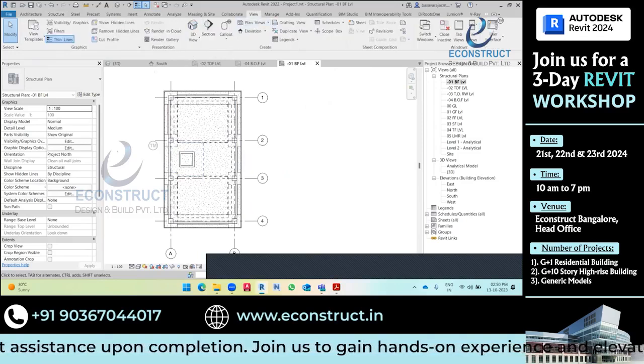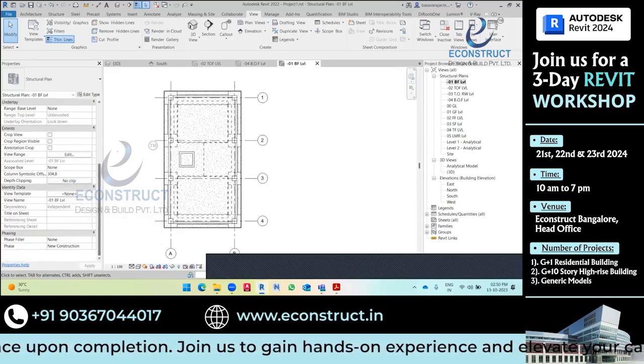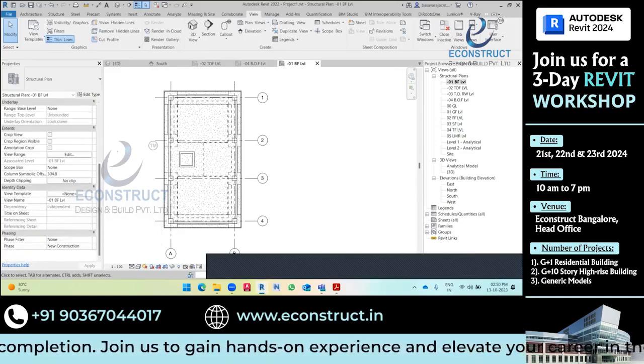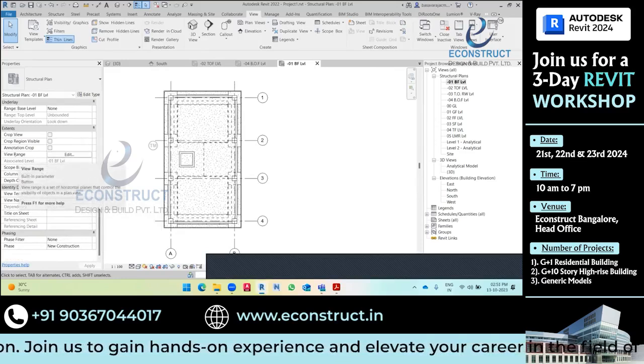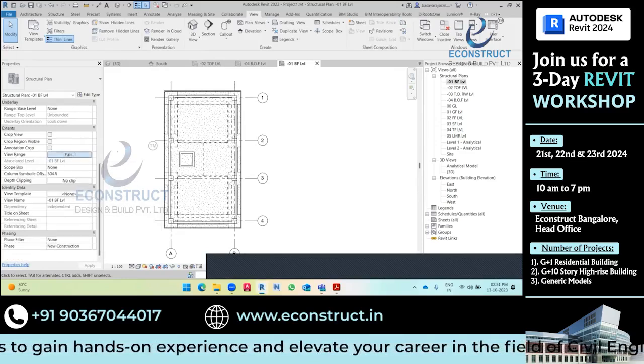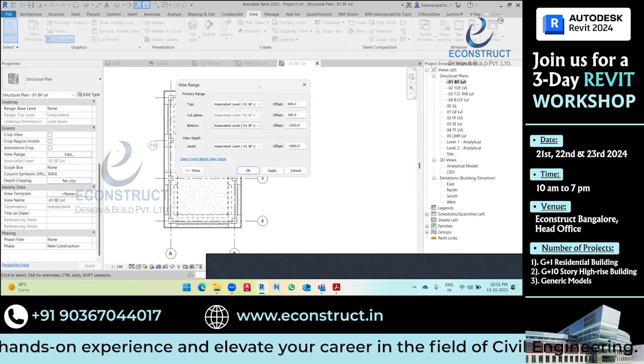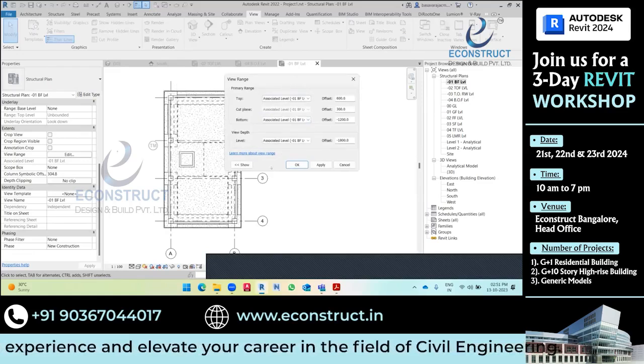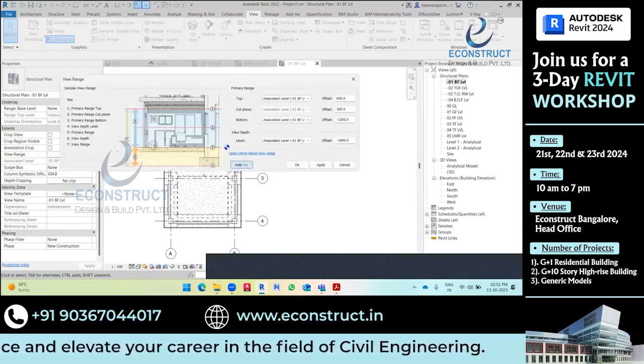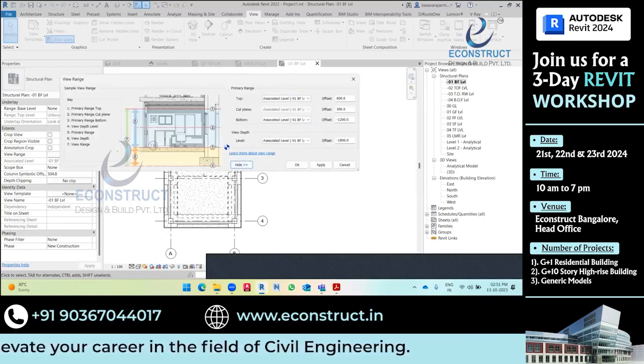Here in the properties panel, view range is there. Just click on edit, and it will open the view range dialog box. Just open this show button. See here, it is there.